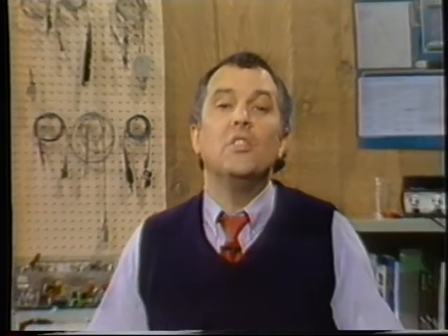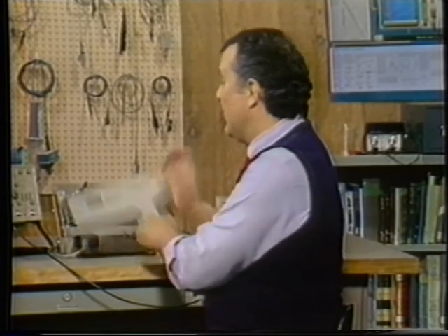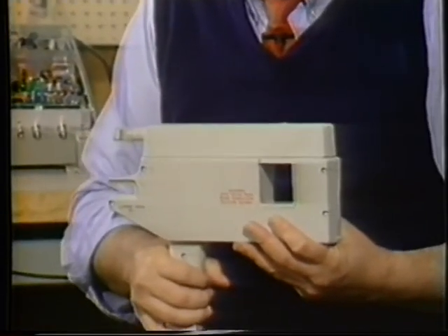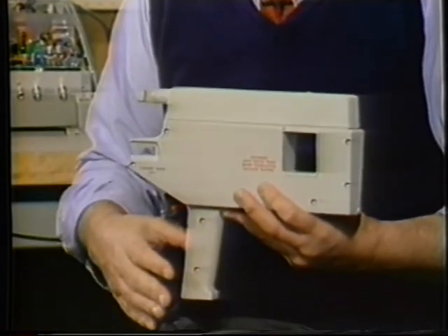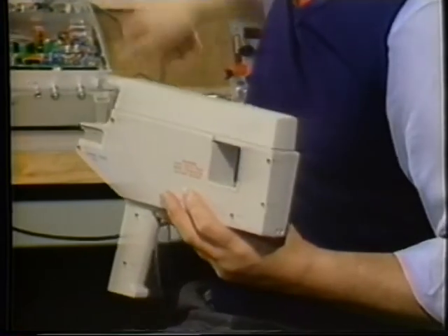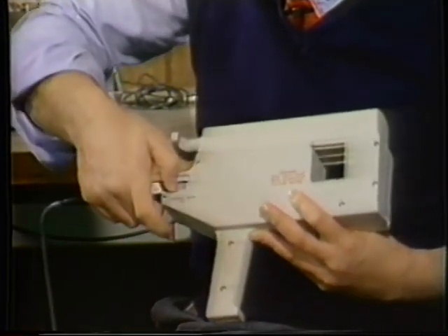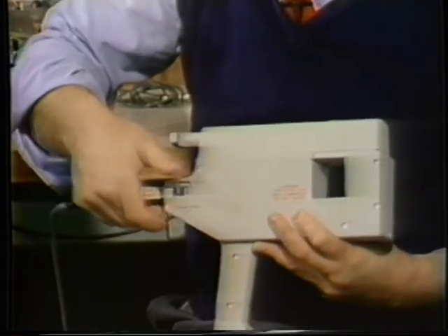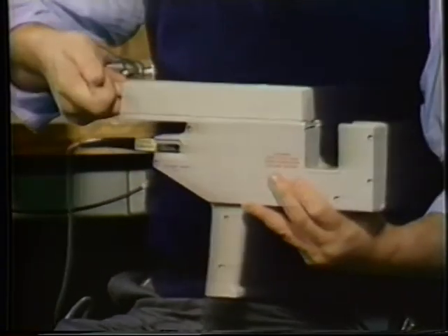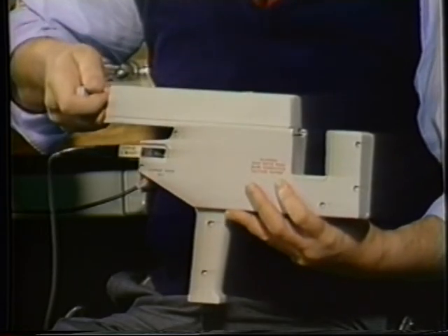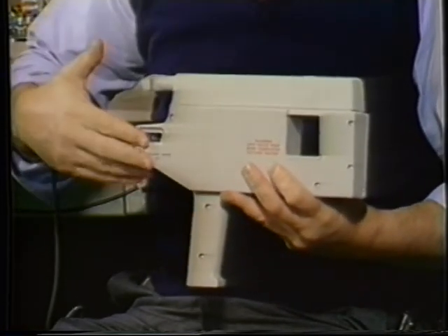Or you could not cheat at all. This monster here is another current probe. It uses a transformer to step down the input current to a level measurable by a second current probe attached to it. And that happens something like this. Now we can capture currents flowing in really large conductors. Using this probe, currents up to 700 amps RMS can be safely measured.